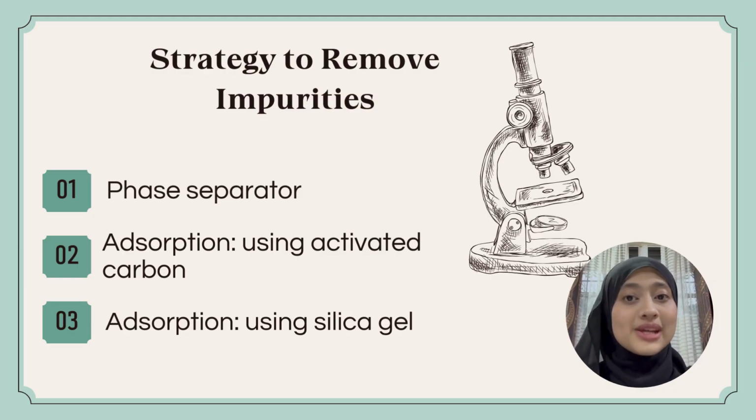To ensure complete removal, we will use silica gel as the final adsorbent layer. Silica gel has a strong affinity for water, effectively capturing any remaining moisture while also helping to eliminate the last traces of nitrogen dioxide. By implementing this two-stage adsorption process, we can significantly improve the purity of the final gas stream, ensuring the highest purity of nitric oxide.